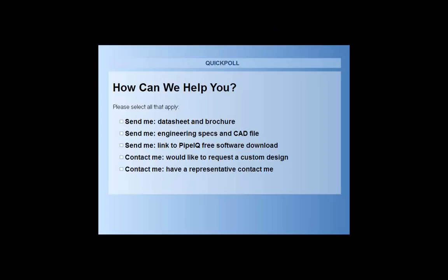Depending on the system itself, me personally, if you have an above-ceiling application, obviously you don't want an end cap with a hole if you're using capillaries, because you're monitoring a void as opposed to monitoring below the ceiling itself. When you do the design, it's going to give you a sample port on it. But what we would recommend is putting no hole on the end cap unless you really need it. You have the option of toggling between a sample port or no sample port.